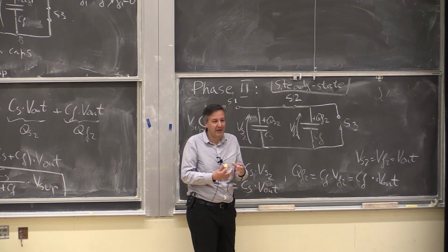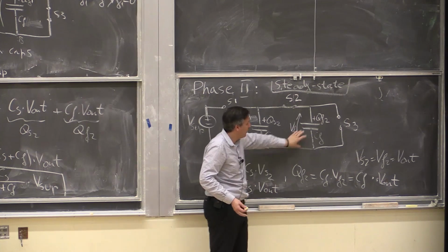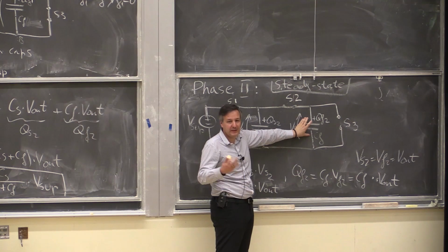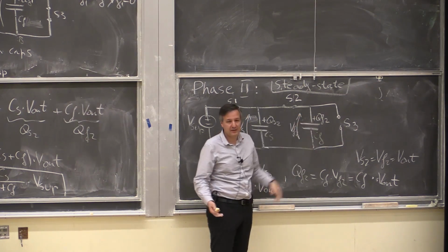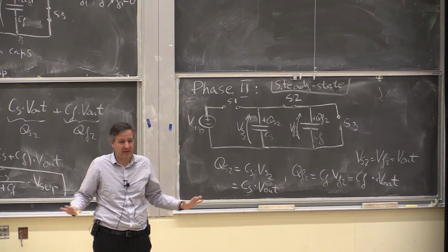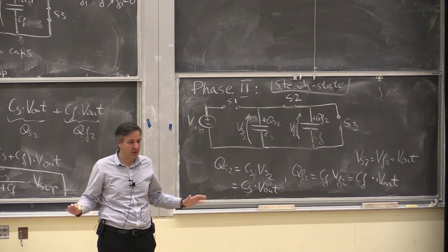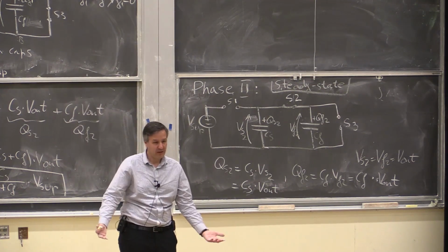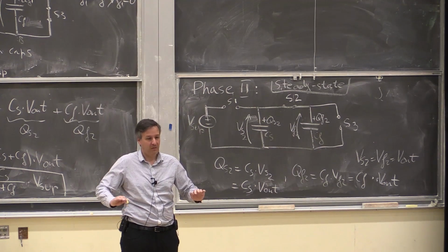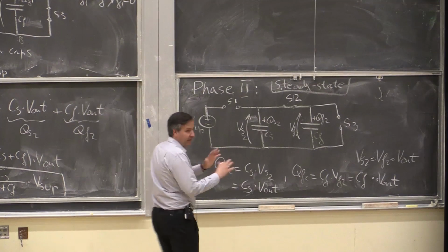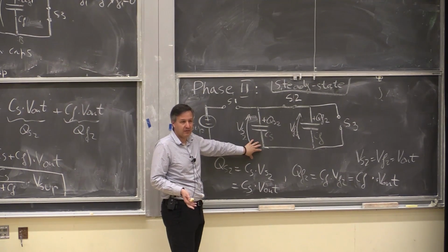But we basically look at the time when the capacitor voltage has actually settled to a steady state value, a fixed value. That means the current here is 0. There's no more current, no more flow of charge, everything's quiet. Charge has redistributed. If you think about buckets of water, you added a pipe, the pipe drained the bucket, the levels are now equal. Now you come back and say, okay, what's the level? So that's how we're looking at this circuit.